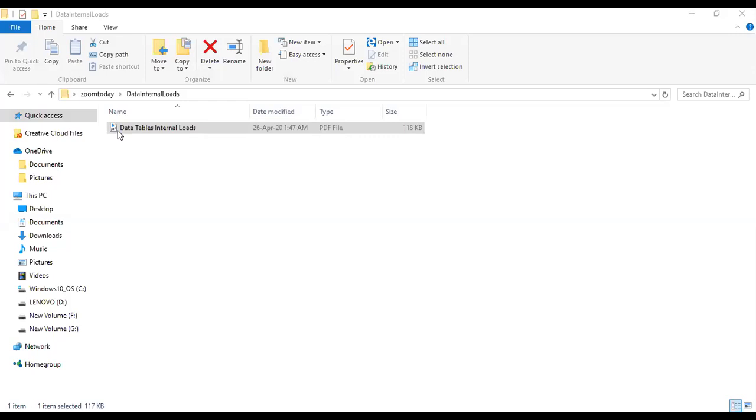You know, these property tables are very, very important for calculation of heating and cooling load. So this is the cooling load factor for lighting. We have discussed this topic, CLF. For CLF, go to this table. Here it shows the number of hours after lights are turned on, because CLF is a measure of how much time it takes to transfer the radiation load to the machine. And these hours should be known: when lights were turned on, when AC was turned on before, during the cooling process. And now, fixture: X type fixture, Y type, two types of fixtures are mentioned.